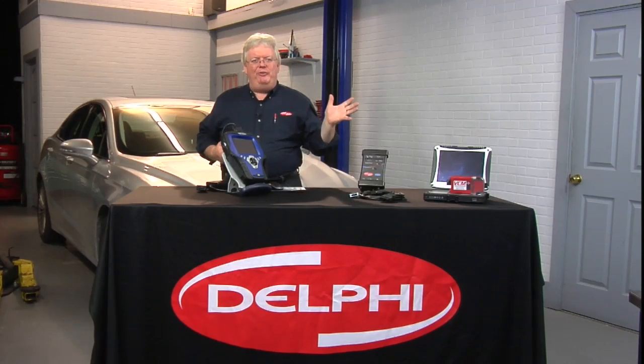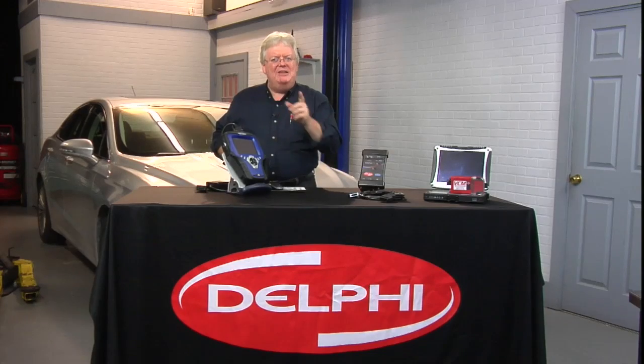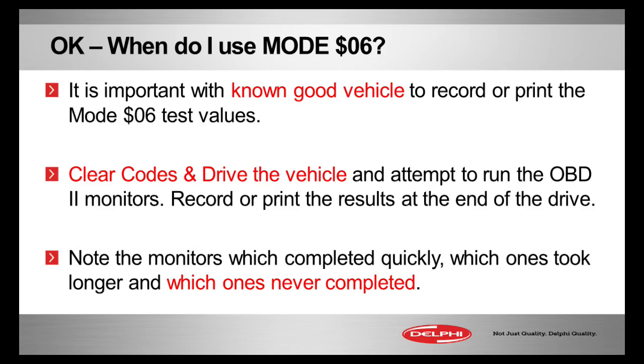So as we said before, clear the codes, make those monitors run again, do the drive cycles, and we know that it may be difficult, but also look to see which monitors don't run. So which ones ran quickly, which ones took longer, and the ones that never completed.